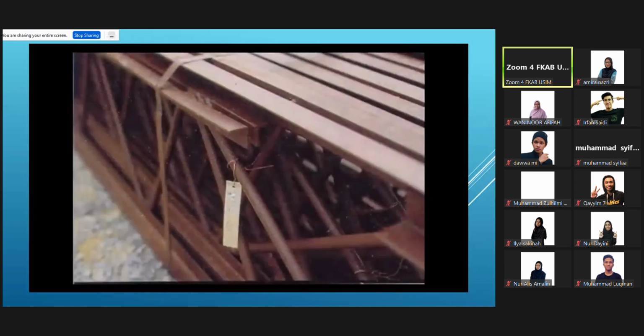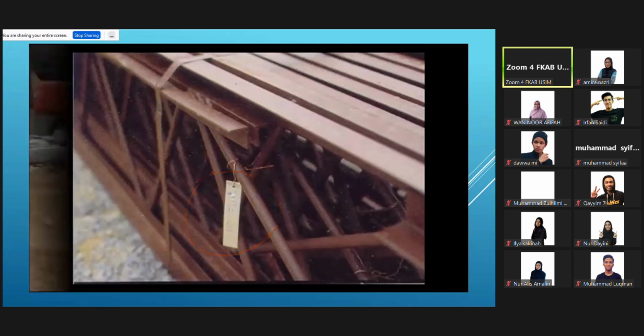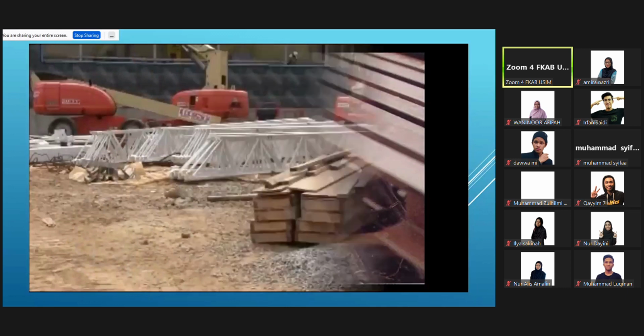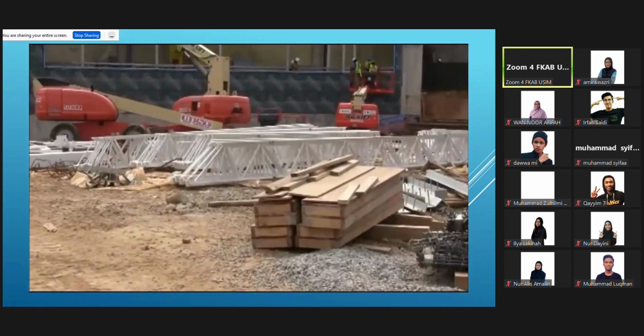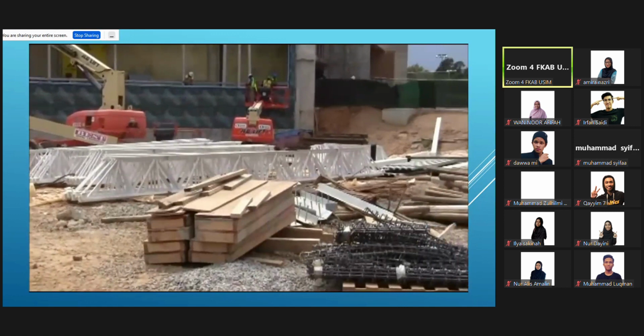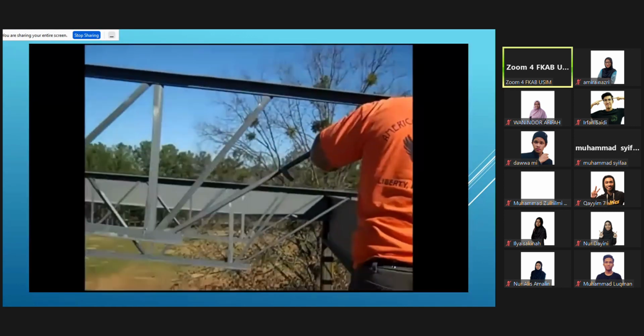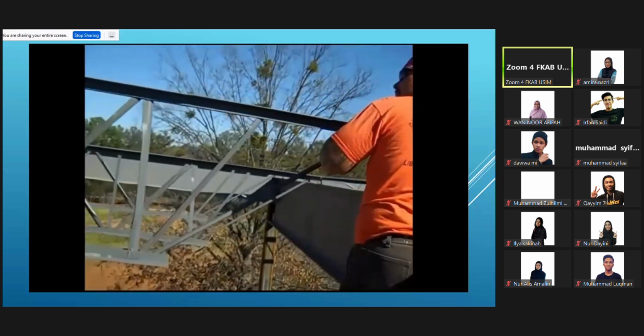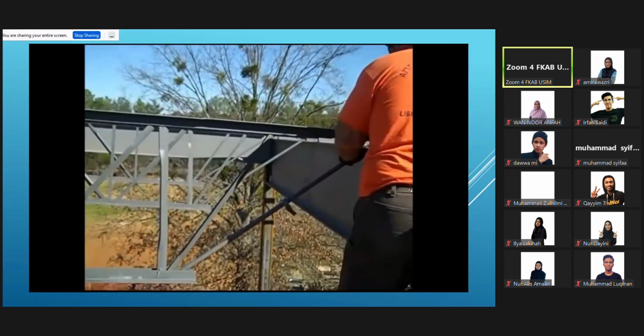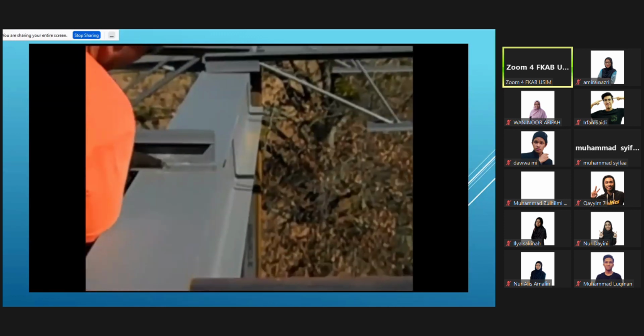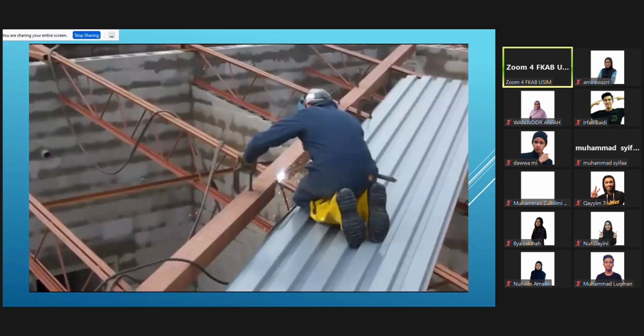Each joist is typically tagged, identifying its manufacturer, sizing, and area of placement within the project. As you can imagine, with most projects, there are a lot of different bar joists being used, so knowing where within the project those joists fit makes it much easier for the iron workers during installation. They can be installed using either a bolted or welded connection, or a combination of both.